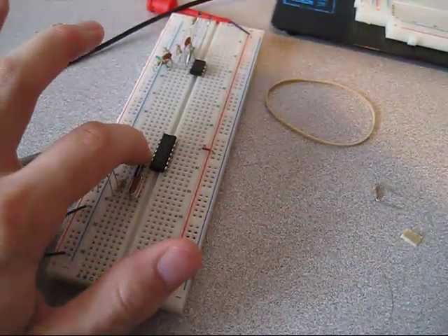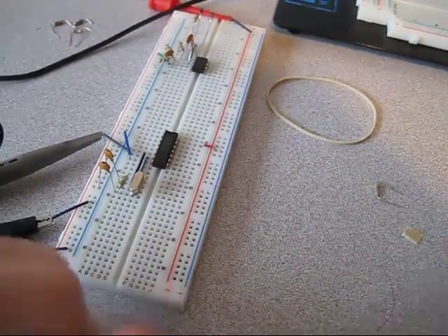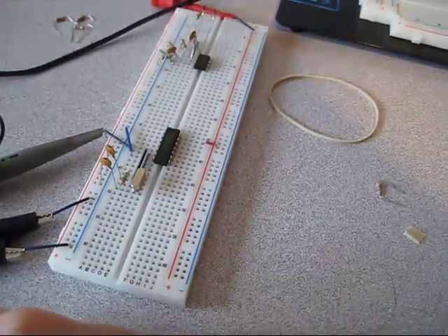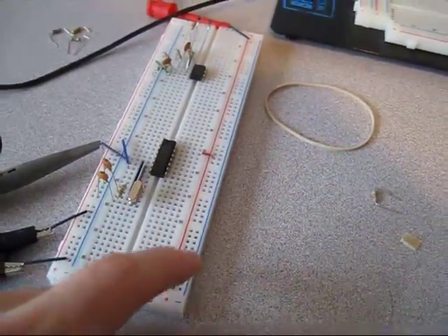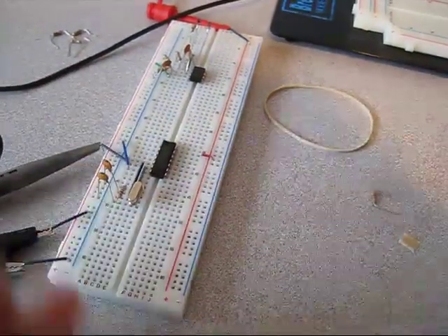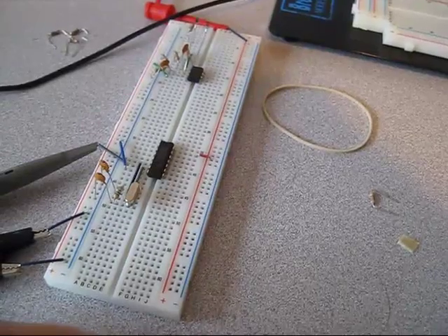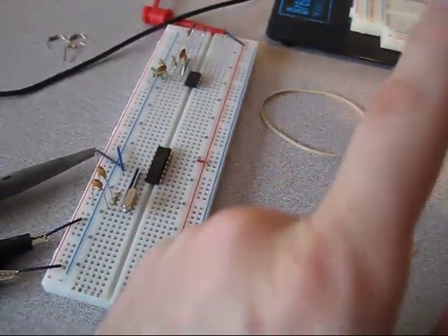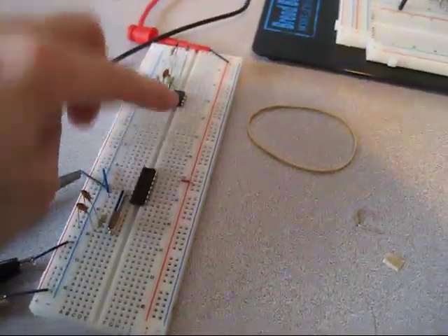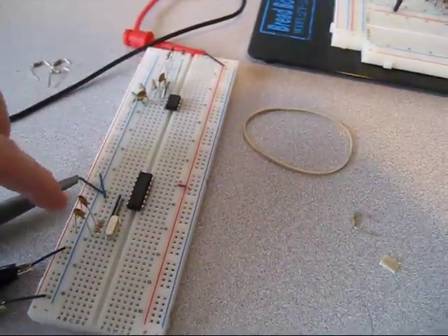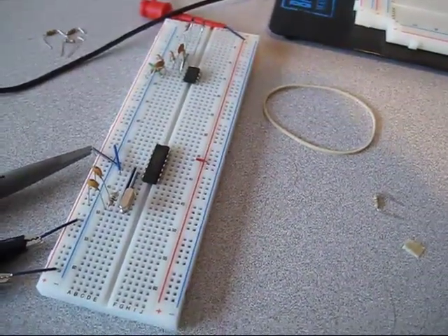I'm also not using that series resistor that we didn't talk about, but I did mention when we were at the whiteboard. That's not being used in this. Usually you'd use something around maybe 2K or so. But we'll still be able to see what's going on in the scope. So also, the other change that I've made is that we're not using dual supply anymore. We're just using the 5 volts and the ground. So let's take a look at the oscilloscope.